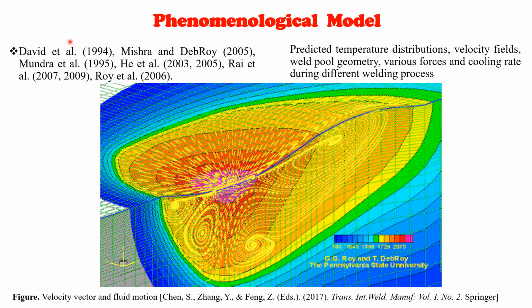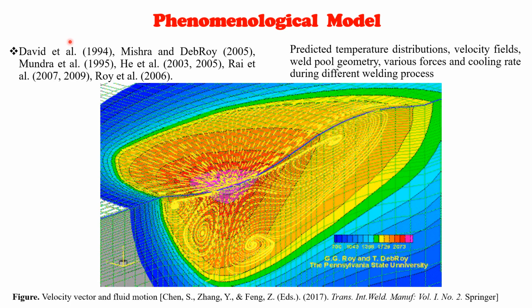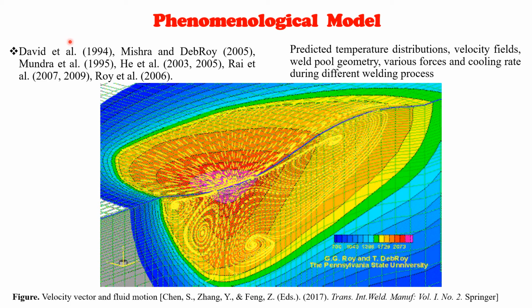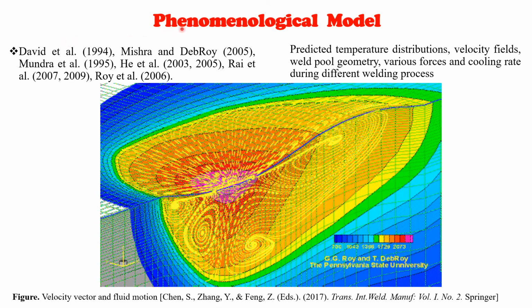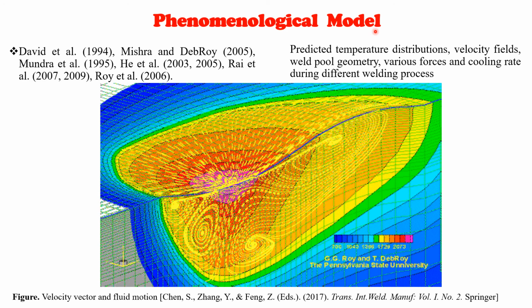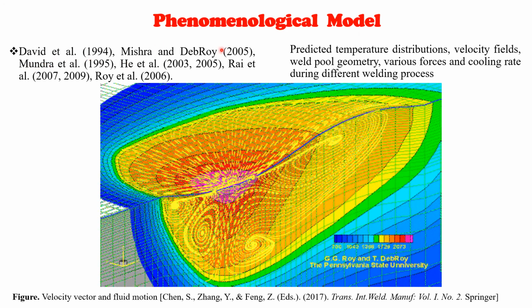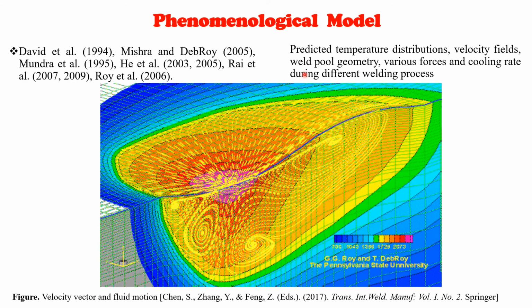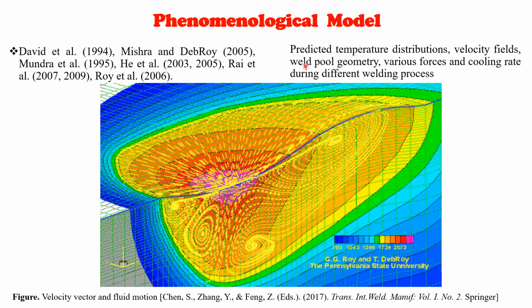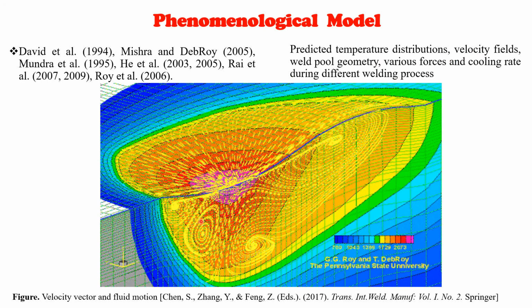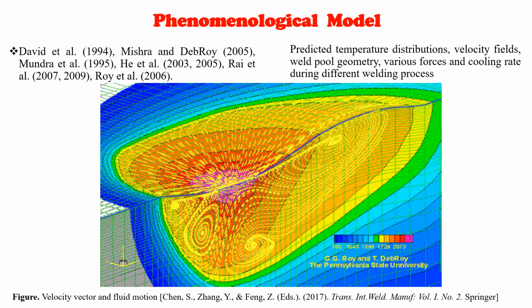Now, if we are simulating different aspects of fluid flow, then why not welding? We have the provision to simulate welding using this CFD based phenomenological model. Many researchers such as David et al., Mishra and Debroy, Mundra have used this phenomenological model to predict temperature, melt pool flow velocity, weld pool geometry, and various forces acting in the melt pool.